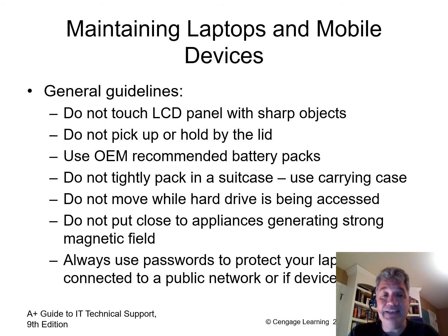If your device gets really hot or cold and then comes into a temperature controlled space, it can cause problems with condensation, which can create all sorts of problems. If you happen to leave, for example, your laptop in your car on a winter day or overnight and it's below freezing, it's a good idea to be on the safe side to let your PC sit for several hours to become acclimated to the indoor space before turning it on.